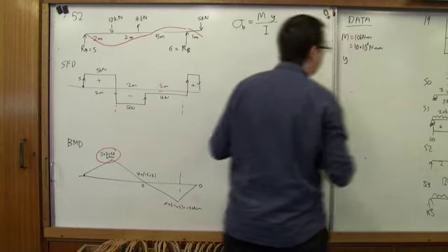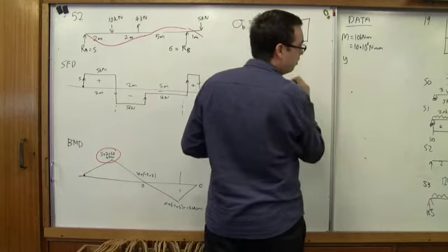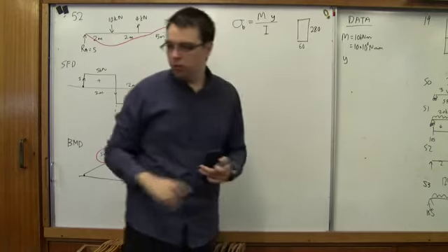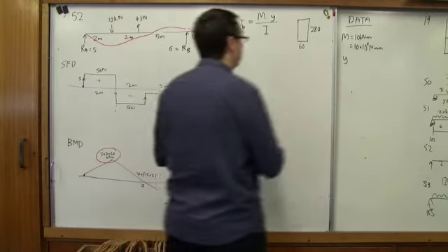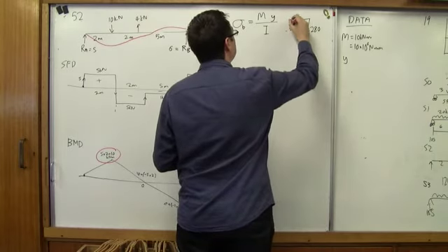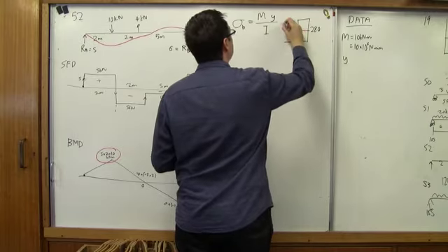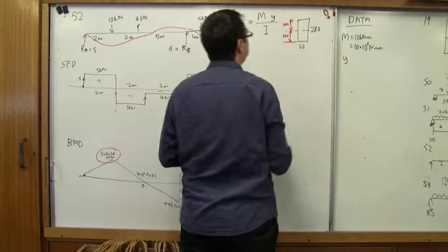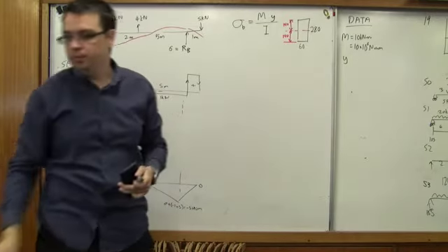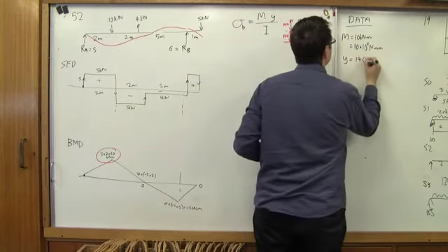Why? Well, to find out why, we need to know the properties of this material. We're told that it's 60 and 280. Because it's rectangular, we can quite reasonably assume that the neutral axis is going through the middle, which means that it doesn't matter if we use y to the compression or y to the tension, it's going to be the same, 140. But if in doubt, we typically use the larger value, right? Big Y is critical. So Y is going to equal 140 millimeters.